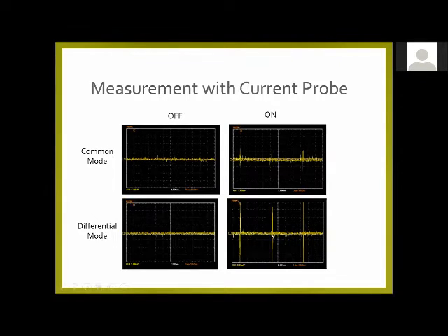But the strange thing is this higher current for radiation purposes usually doesn't make as much noise as the common mode current, because you have current going one direction and right next to it a wire with current going the other direction, and the fields from those two wires generally cancel themselves out mostly as you get farther and farther away from the wiring. The common mode current, on the other hand, since it's always the same direction in all the wires, acts the same way an antenna works, and that's why it's called antenna current. And it can really produce a lot more radiated emissions per microamp.